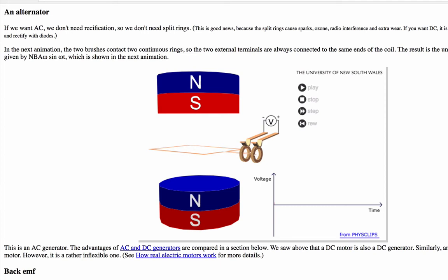So we're going to look at exactly what is the shape of the voltage or EMF that is going to be generated by this loop as it turns. Now, to begin with, as you can see, the loop is horizontal and the field lines are running vertically. So at the moment, the flux is at a maximum, and maybe you can take a second to think: if the flux is maximum, what should the voltage, which is the rate of change of flux, be to begin with?